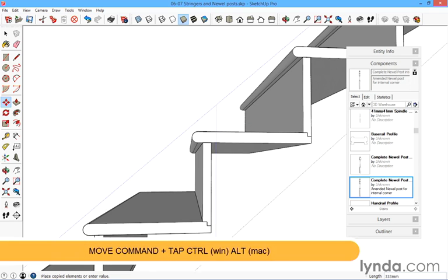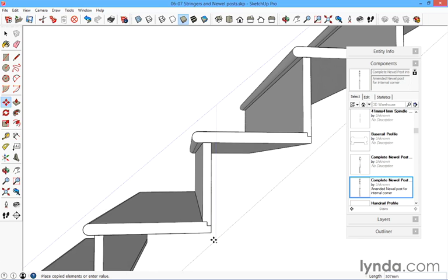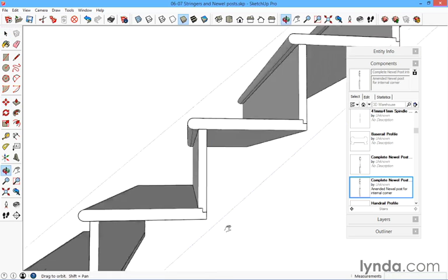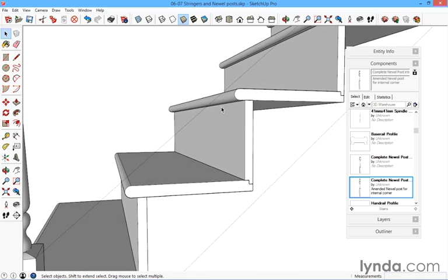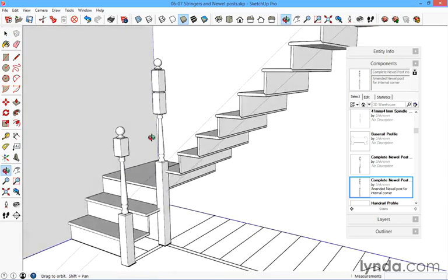And let's come down on the blue axis. We've got 320, so maybe 310. That's a foot. 310. And then that gives us a depth for our stringer. Now the width of the stringer is going to be about 38 mil, inch and a half. So we've got that sorted out.